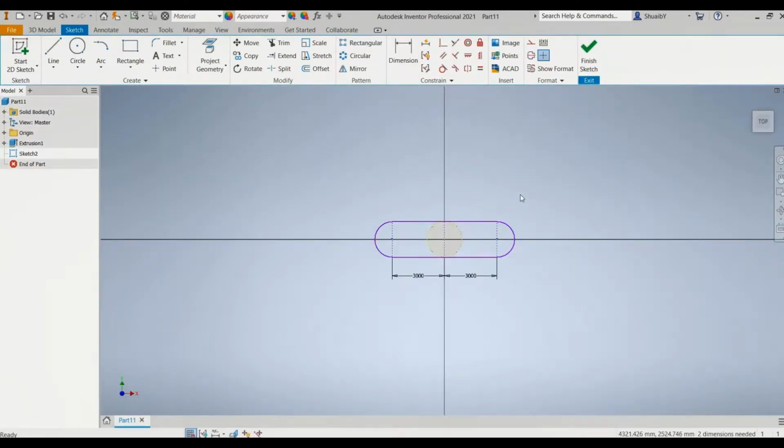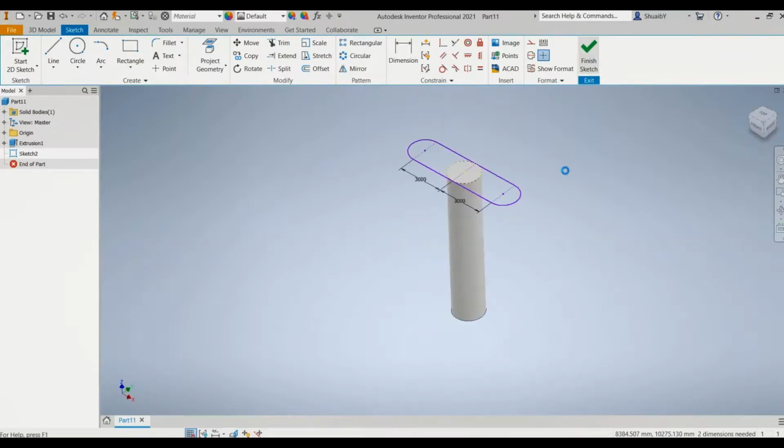Okay. So what we're going to do now is confirm that the constraints are met. Where is this button again? I'm looking for show constraints. As you can see, I am an amateur in Inventor, so bear with me if I can't find it. There we go. It should be that one. So show constraints. And as you can see, as I'm clicking on the object, it shows me what it is constrained to, and that is perfect. If this was green and not purple, that means something is not joined correctly. But in this case, it's pretty good.